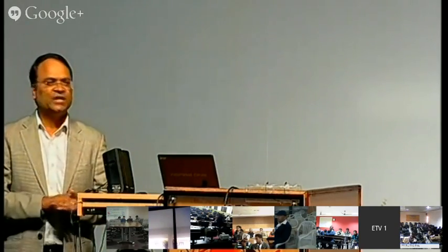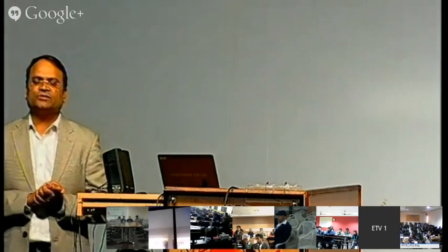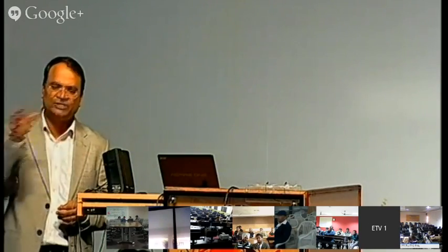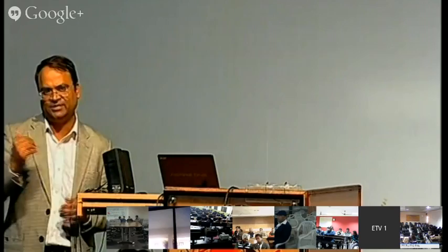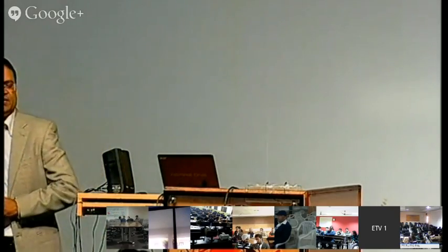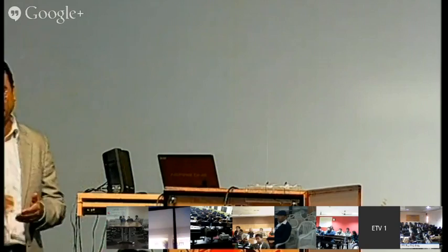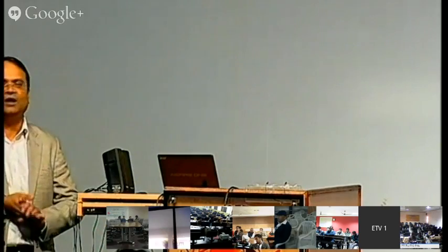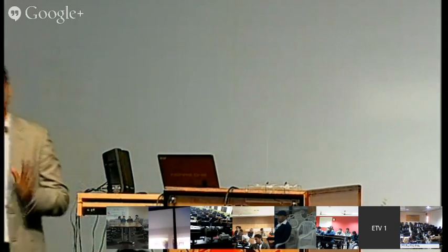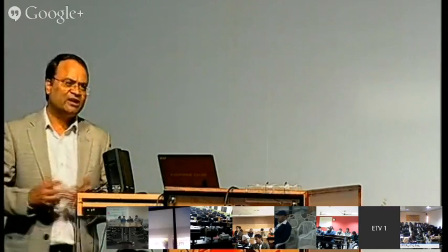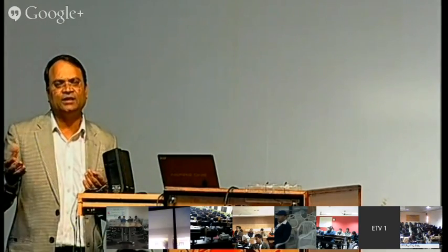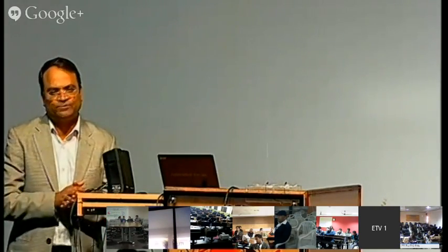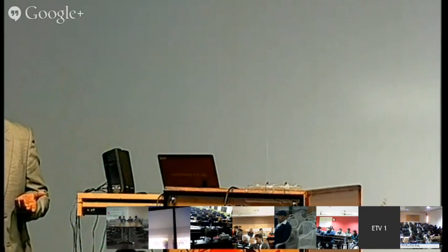Why do I say chances? Because with reciprocating motion, reversal of motion takes place, so film rupture will take place at top dead center and bottom dead center. And if the speed is very high, there is a lift, meaning lubrication will prevail at that speed. If that speed is reached and proper film formation is there, then we can say this is the order of film thickness, and that is the clearance. The minimum film thickness is itself the clearance. If film formation is not there, then there is no clearance at all. Metallic contact will be there.